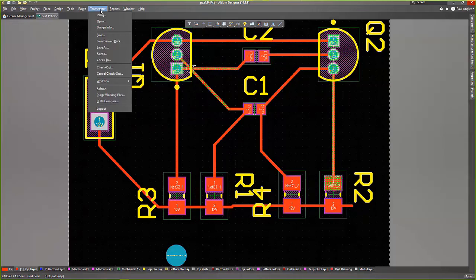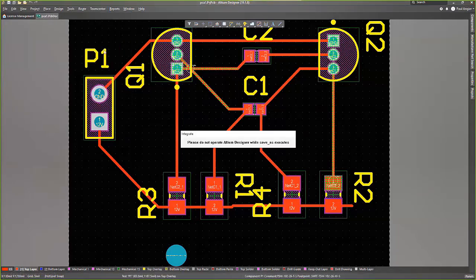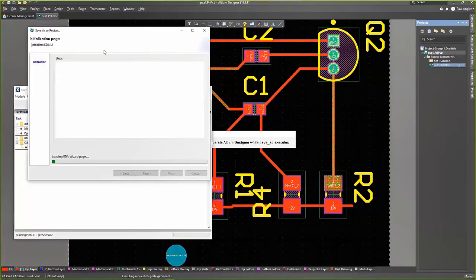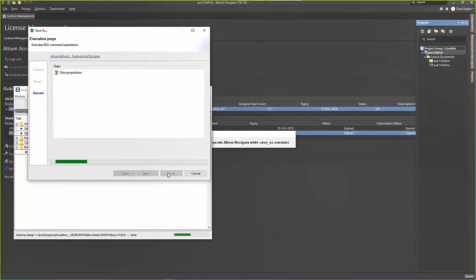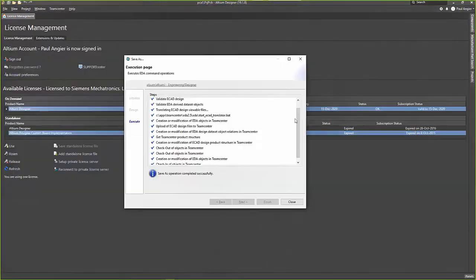All right, so in this demo, you're an Altium user. And just like we do for SolidWorks, we brought Team Center inside SolidWorks. Same thing we do for, in this case, Altium. We bring Team Center inside that environment. So right from inside Altium, you as a designer can come through and save your design into Team Center. So you can save your printed circuit assembly, which is going to give you the bill of material. You can even have it create all the manufacturable components like the Gerber file and the ODB++ and so forth.